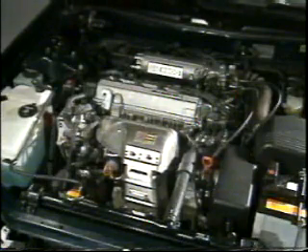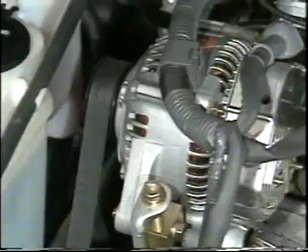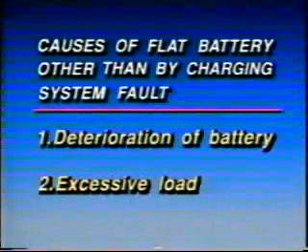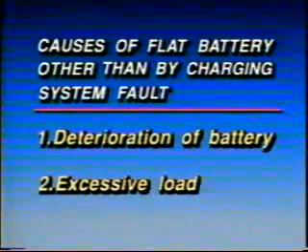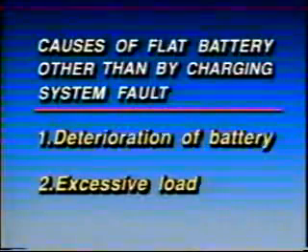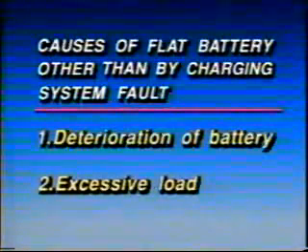One of the commonest faults is a flat battery. However, a flat battery is not always caused by a fault in the charging system. There are also other causes. One of the causes is deterioration of the battery. The other is overload. In other words, the vehicle is provided with more electrical components than specified by the manufacturer.